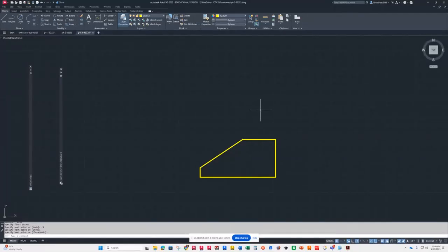So step 2, do we go with the top or do we go with the side? Well, I think I'm going to draw the top, so I need line. And I'm just going to hover over this guy, bring him up, and draw me a line. Lines up with this guy, like so. Or make it 4 long. And then I look at how deep it is. It says it's 1.75, so 1.75 deep. And then I'm just going to finish up my box. Yes, I could have used the rectangle command. That would work.